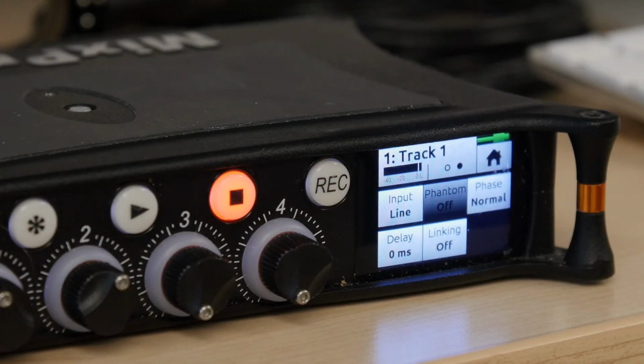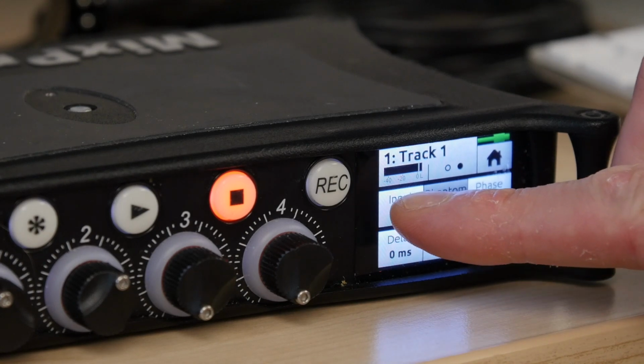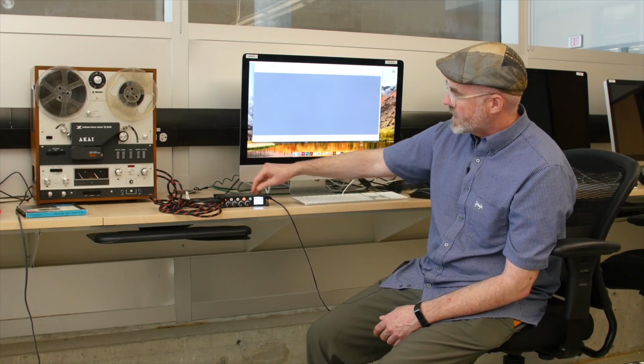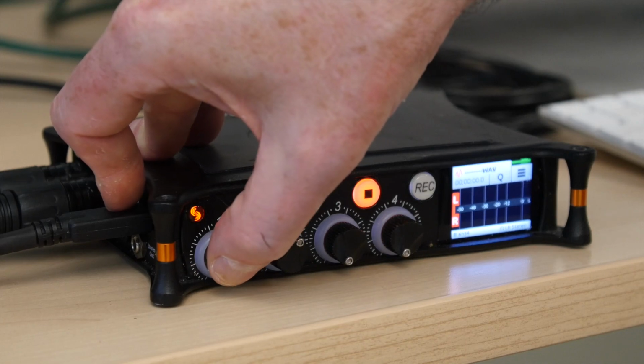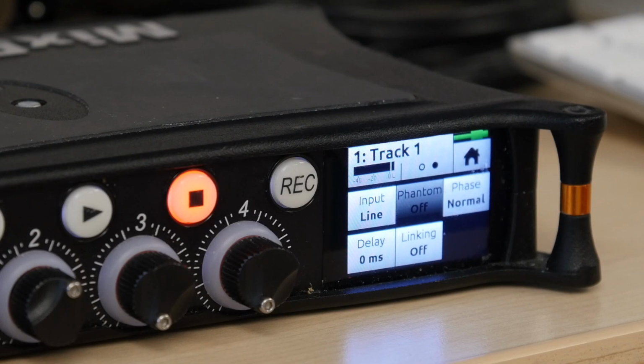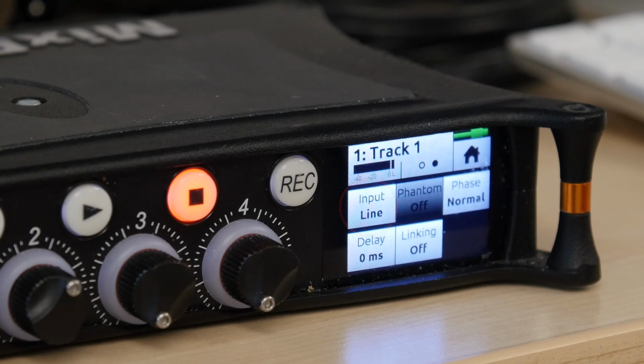And the thing we want to keep in mind as well is what levels are we bringing it in at, and it's line level. And the difference between line level and mic level is about 10 decibels. Line level is about a 10 decibel pad. And so we want to be sure if when you bring your audio in and you're like, oh, it's really loud, you want to check and see, okay, is it at line level or mic level? And so the first thing we did was we checked, and we just press the number 1 input, and then we were able to see that indeed it is at line level, which is what we want.